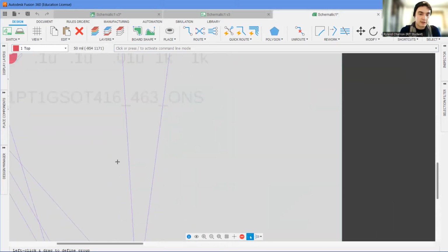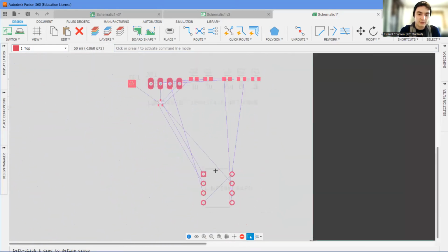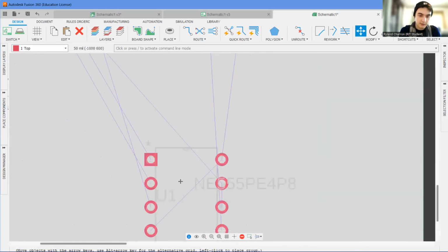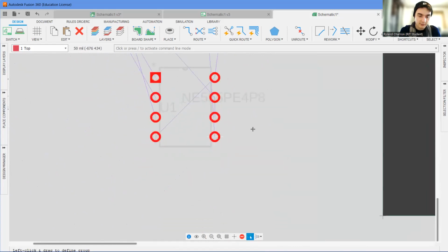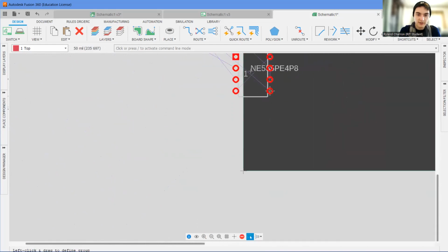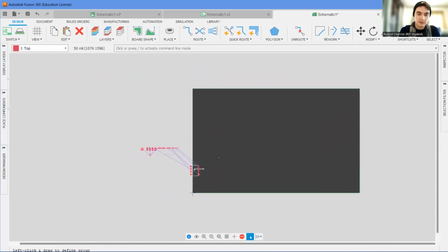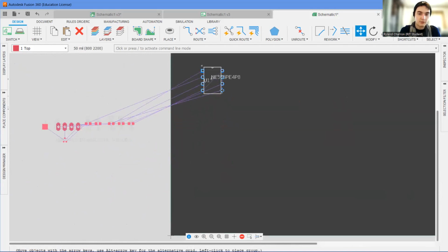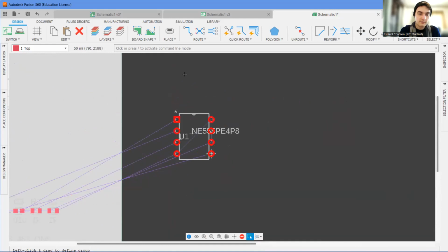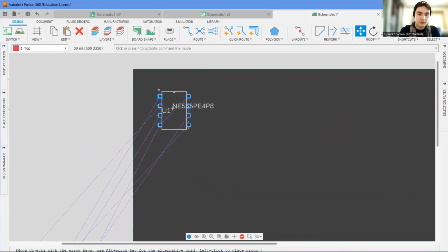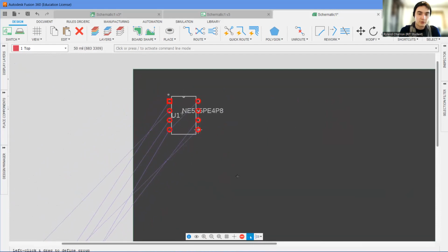All right, we got all these things. They're a mess. We have to put them on the board. So again, we got to find the origin. There it is, the plus sign. It's really hard to see. The white plus sign there on this pin. And we're just going to drag this onto our board. So the board is the black space. And we're just going to stick that up in the top corner. We're not going to use the whole board, so we'll trim it in a minute.